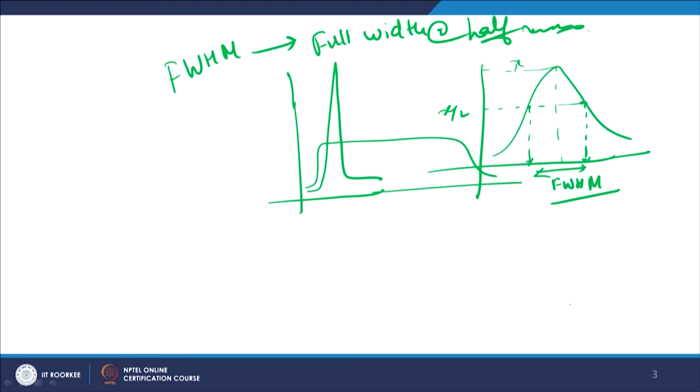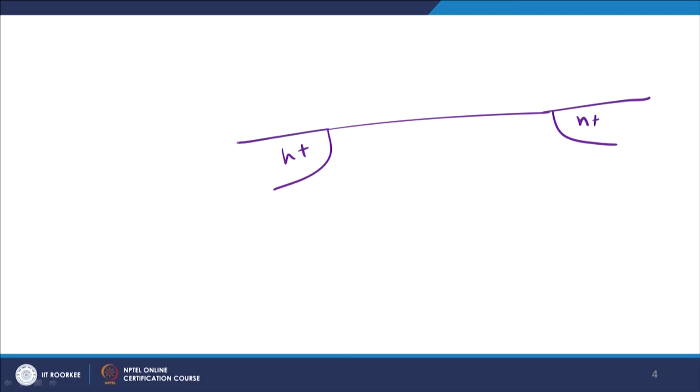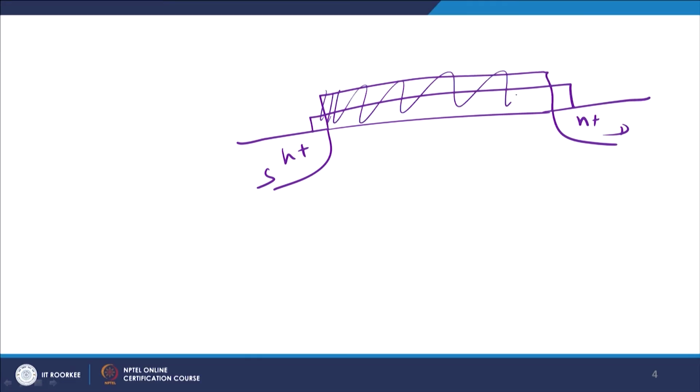An important point in current technology is that you require self aligned processes. Self aligned primarily means that, let us suppose you have a device which is something like this, this is your N and this is your P, N plus and N plus, and this is your source and drain, right, and if this overlaps, so you are overlapping with it. Self aligned means that the alignment of the oxide and the metal is exactly that of the source and drain material, and that is how you do it here.